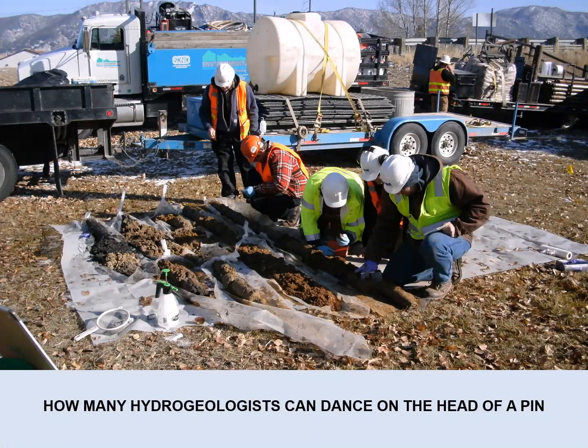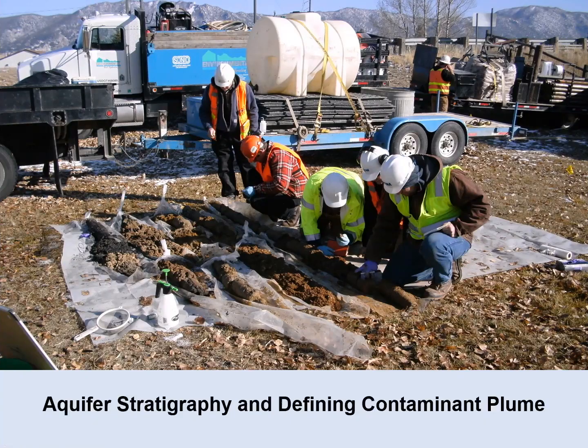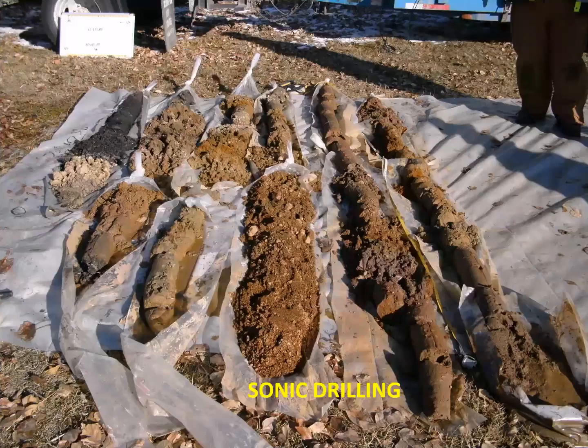So again, this was sonic drilling. It created a continuous core, and the core came out wrapped in those plastic casings. Unlike the drilling with air, you could get a really good view of what the stratigraphy looked like. So right here, we're talking about a nice sand zone. You can see how it just fell apart. And right here, we're talking probably pretty clayey material. Again, that's just a close-up of the same thing.